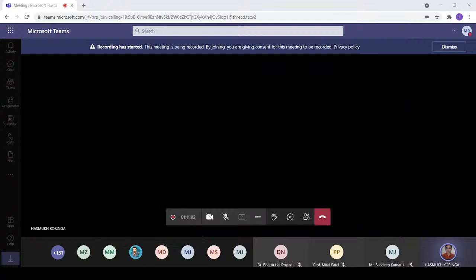And third is assembler. The assembler, as we know, generates a programming file for that particular device. If it's an FPGA chip, then the programming file format is SRAM object file. And if it's a CPLD programming device, then the programming file is .POF, programmable object file.